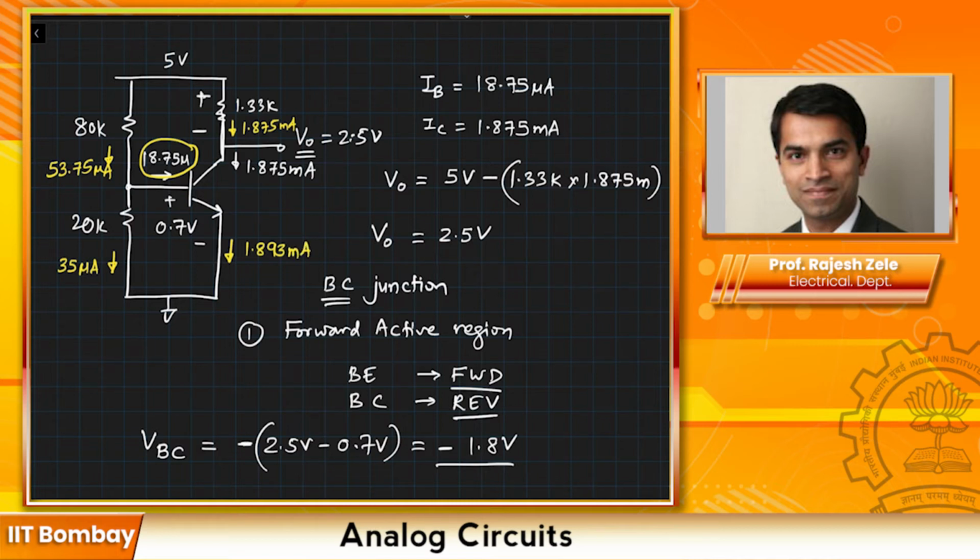So this is something we already learned, called the DC operating point of the transistor, where we are meeting all the requirements or conditions of operation of the transistor in a proper region of operation. For example, if you simulated this circuit using a SPICE simulator, then you would see these numbers at different nodes and these currents in different branches. So our job of DC operating point is now done. Now we will figure out how this circuit behaves as an AC circuit. When I apply a small signal voltage, how does it work?